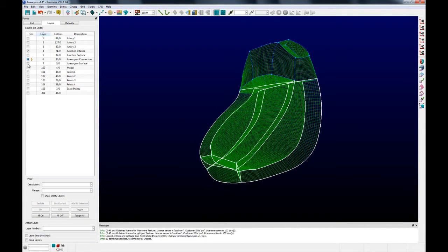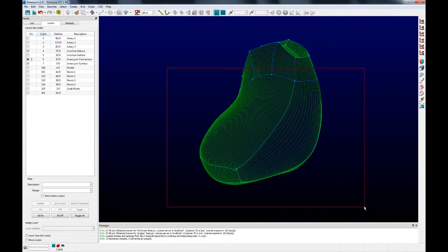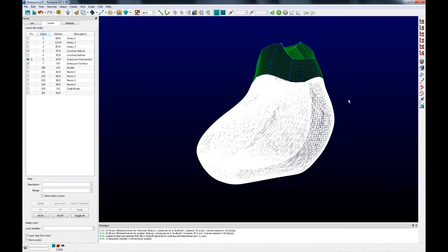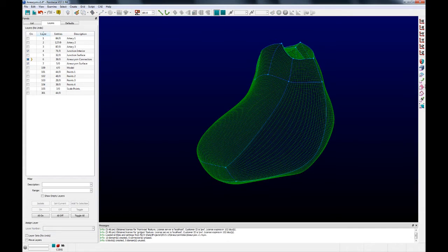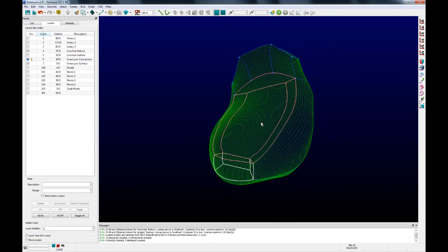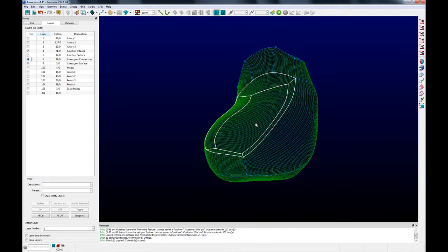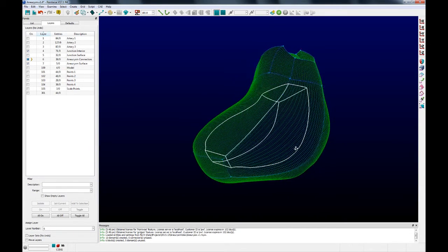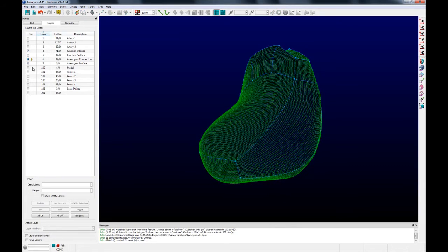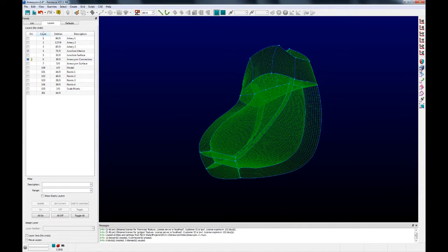We'll go ahead and turn on the surface. We'll change our selection mask to include domains. We'll highlight all these domains and click on Assemble Blocks. By doing so, we create 6 blocks, which is what we expected. We have the tip block, and then the typical 5, the 4 OH, and then the central H core. So we're looking pretty good. I'm going to go ahead and turn the surface off just for visibility purposes.